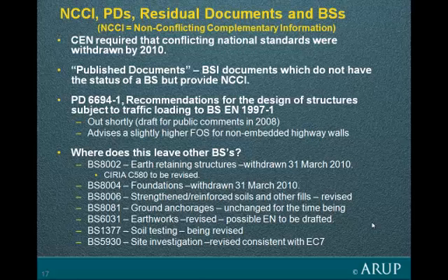Where does this leave the other British standards? Well, BS 8002, for example, is now withdrawn. It was originally nominated as non-conflicting complementary information. It's withdrawn, meaning that it is no longer being updated by BSI. That doesn't mean it doesn't exist, and you can in fact still buy it from BSI, and you may find complementary information in it that is useful. But where it is in conflict, Eurocodes take precedence.